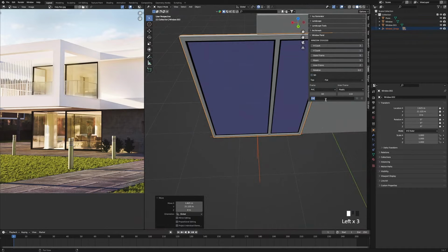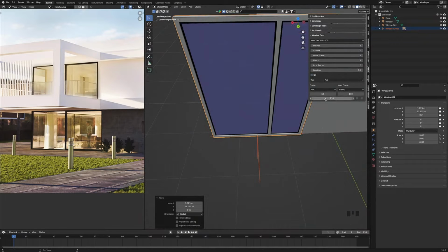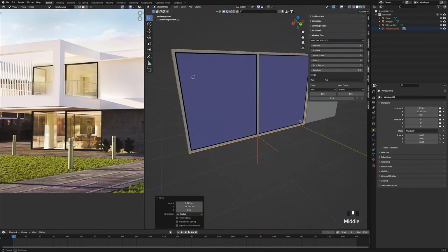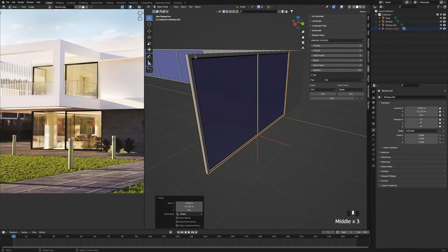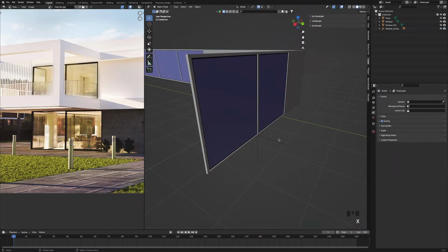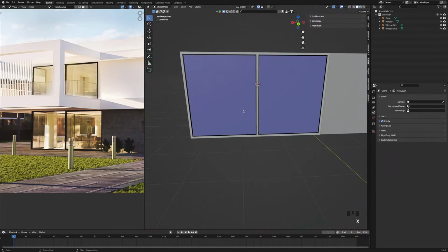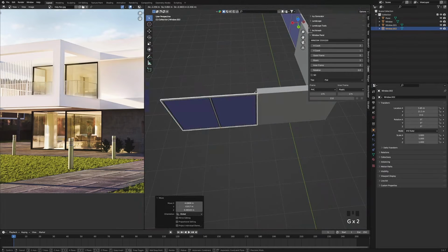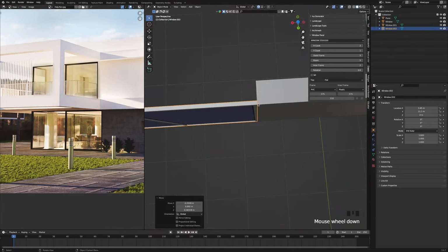We're going to have the height, 210, and the width is going to be 175 for both the panels. And of course, we're going to delete the box empty and the regular one. Make sure it's still selected and turn off all of the locks. And then press G and just snap it like that right at the corner there.